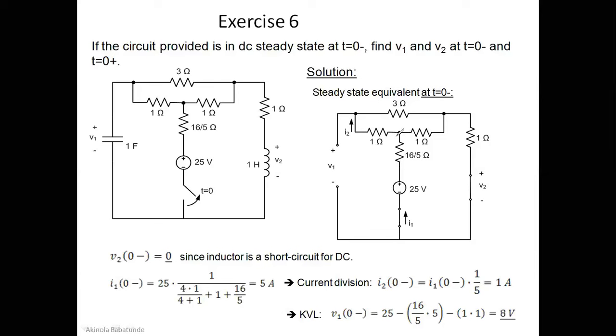to this particular node. Okay, so at this particular node, the current is going to split into the left and then to the right, and then it goes this way. Whatever current goes through the 1 ohm resistor is I2, as labeled in the circuit here. So I2 gets to this node. It cannot come this way because this is an open circuit. No current will pass through here. So the current that passes through 1 ohm will go to this node and then pass through 3 ohms.